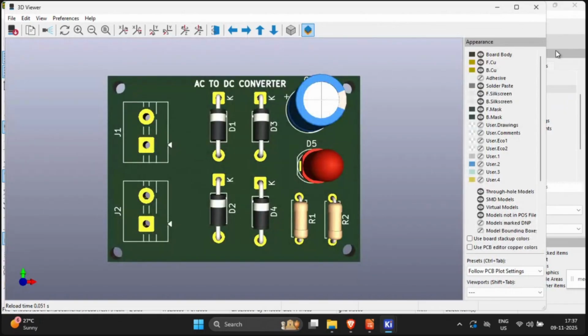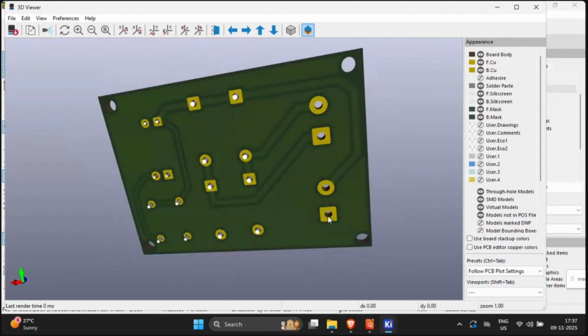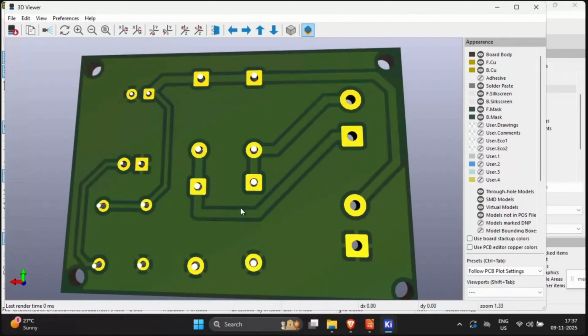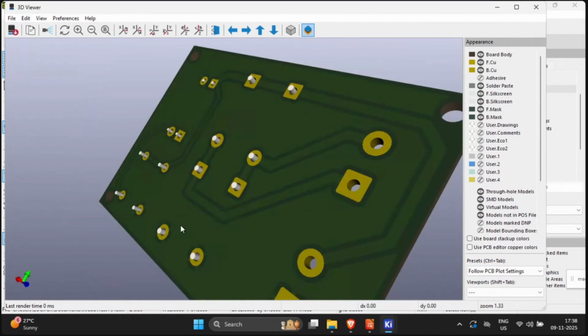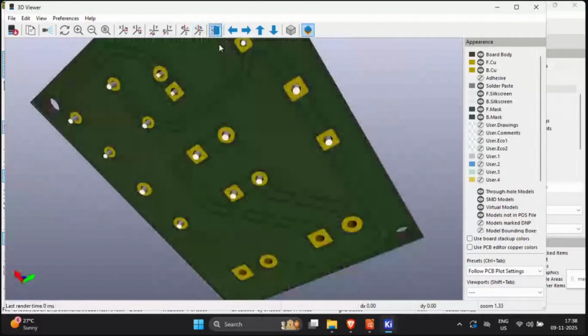You can have an AC to DC converter here, and you can see our trace was on the back side. So this is how our trace is. It's visible on the back side. You can see its edges. The copper from the edges is removed. The center part is acting as our conducting wire. So you can think of it as an insulated conducting wire. Because of that, the entire plate has a copper plating and it's not eroded, and the rest of the plate could be used as a grounding terminal. So you have a common ground as an entire plate.